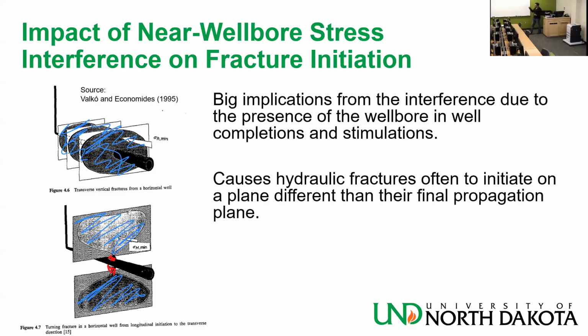And also, when you are producing the well, you flow the other way, you may end up in a situation where the flow is obstructed by a twisting. So you get a well that is not stimulated the way that you wanted, and then it's not producing the way you are hoping. You get two types of problems. This is not good, along other problems, like stage communication, fluid from one stage moving to another, and so on and so forth.